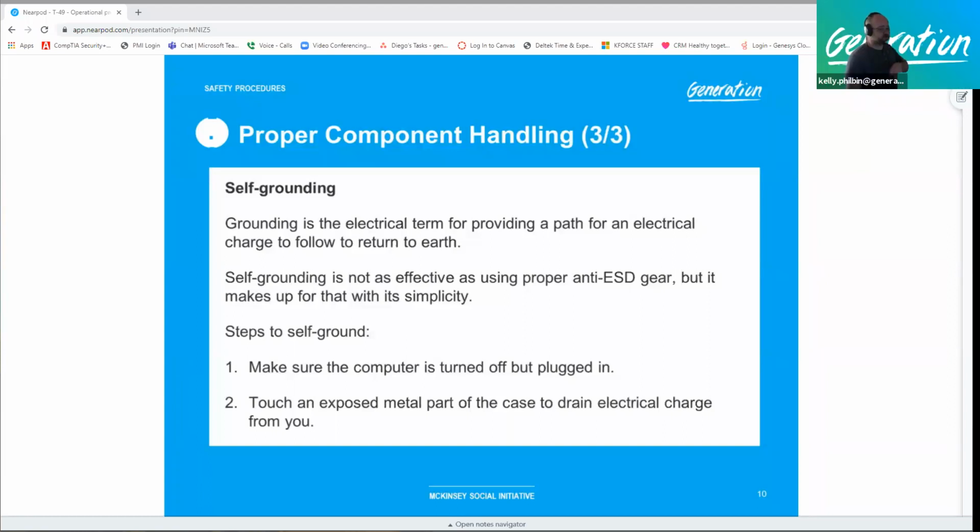Okay, before you ground yourself inside of a computer, what do you want to do? Unplug it. There you go. Turn it off, unplug it, and then hold the power button to get residual power out of it. Perfect. Exactly. That's what we want to do, just to reduce the risk even further of potential shock, especially from a capacitor, because those can do a lot of damage, unfortunately. And you want to make sure you're clipping to a metal part on the computer internally, like the frame.